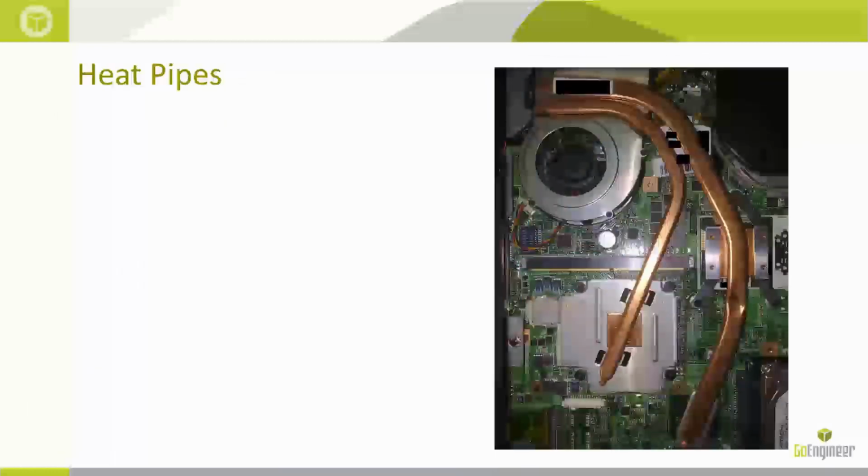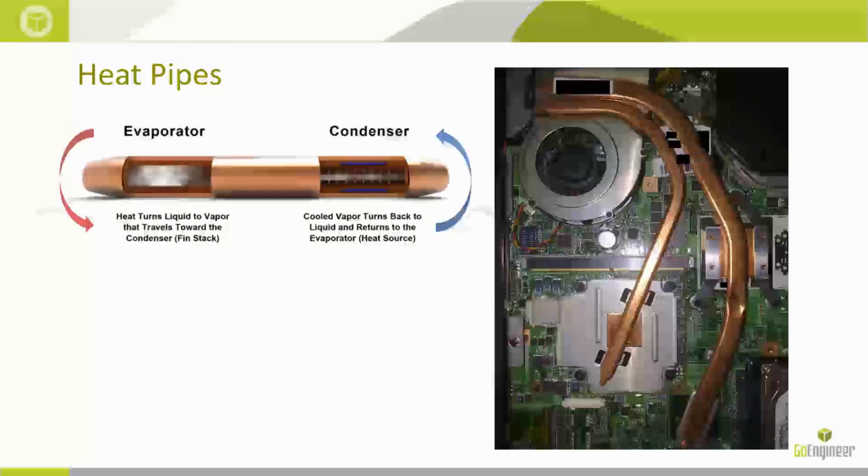And lastly, heat pipes are extremely complicated, and what they involve is one region that has a fluid that evaporates and becomes a gas or becomes a vapor. Why is this done? Because the latent heat of vaporization takes in a lot of heat without much change in the temperature, which is very advantageous from an electronics cooling perspective.